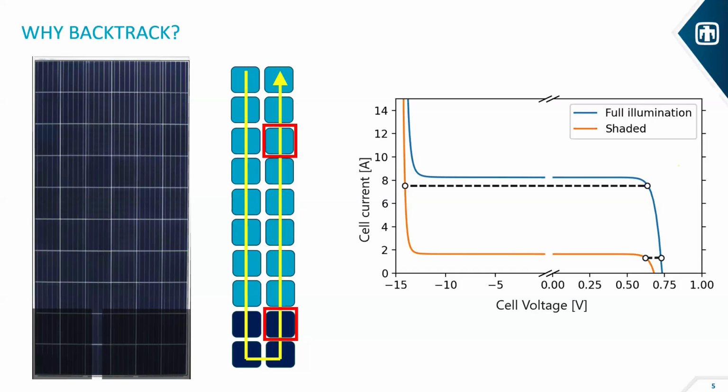They're going to be probably shifted down a little bit because the irradiance is less per cell, the same overall, but we'll be able to get a lot more power out of it and don't have these shaded IV curves in this case because of these mismatch losses.